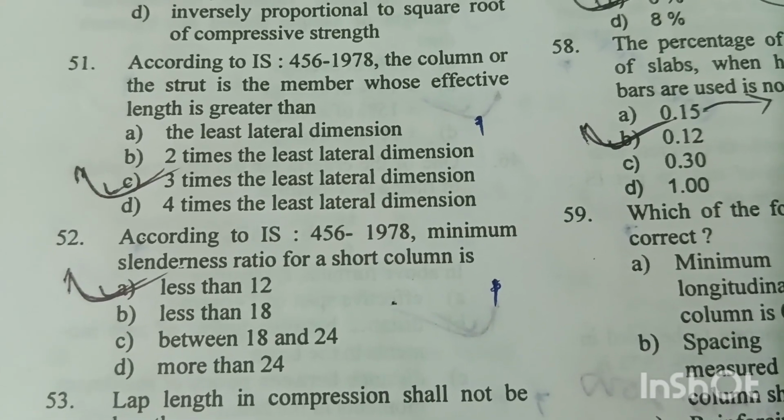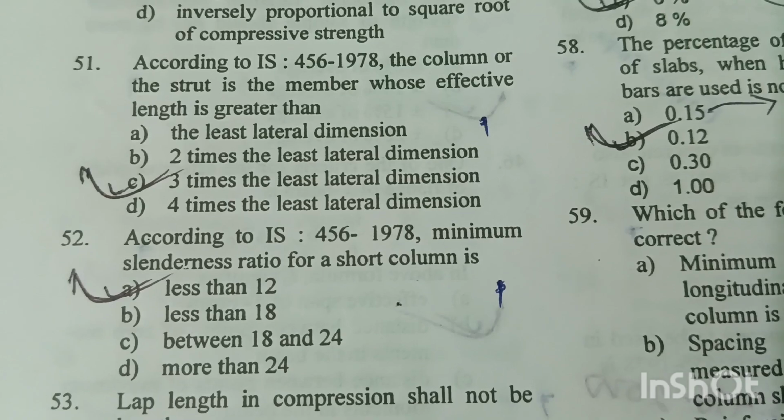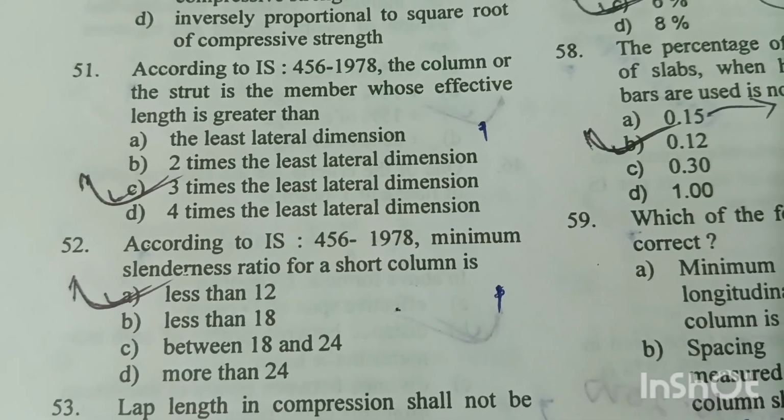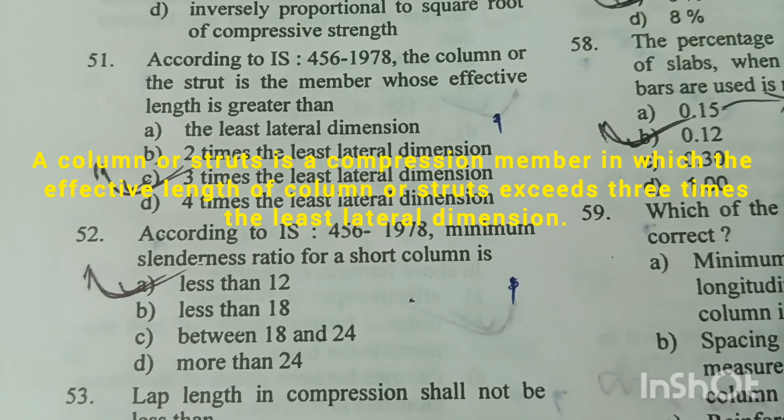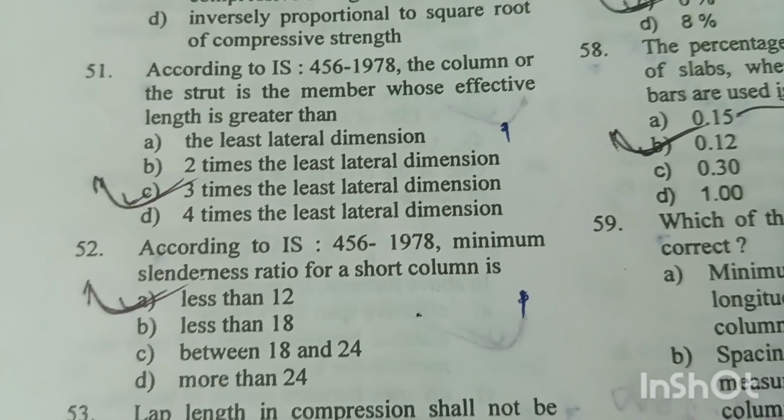Question number 51. According to IS 456 1978, the column or strut is the member whose effective length is greater than 3 times the least lateral dimension. Option C is the right answer. Otherwise, it is called a pedestal.